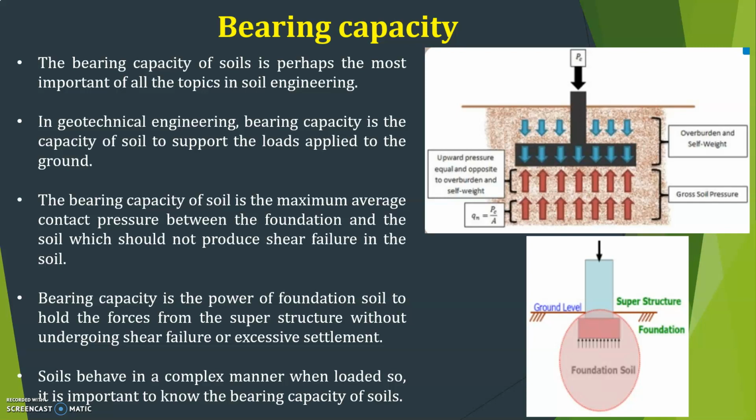In geotechnical engineering, bearing capacity is the capacity of soil to support the loads applied to the ground. The bearing capacity of soil is the maximum average contact pressure between the foundation and the soil, which should not produce shear failure in the soil. It is the power of foundation soil to hold the forces from the superstructure without undergoing shear failure or excessive settlement. Soils behave in a complex manner when loaded. So, it is important to know the bearing capacity of soils.